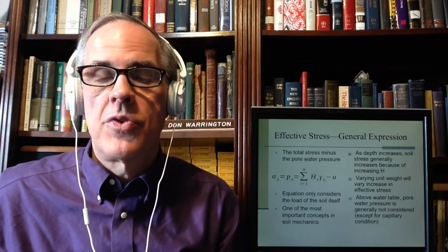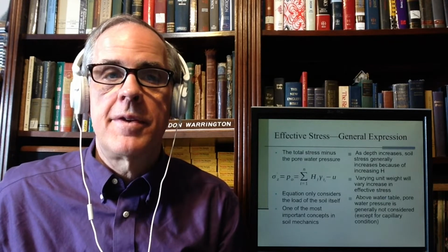Generally speaking, soil stresses increase as you go further down because of increasing height and weight on top of it. Varying the unit weight will vary the increase in the effective stress, obviously. Above the water table, pore water pressure is generally not considered except for capillary conditions.